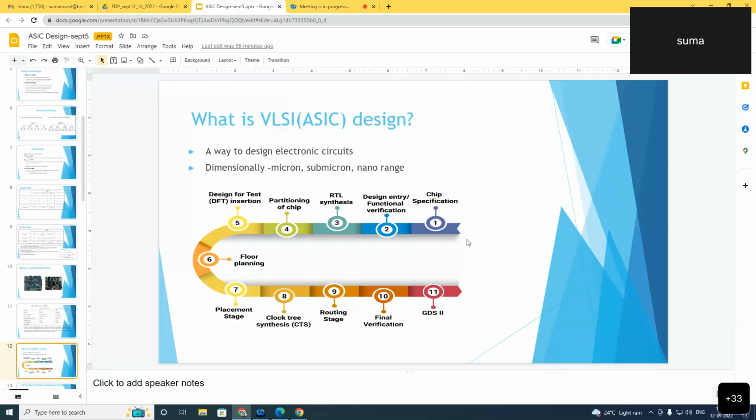Power also depends on the material used to fabricate the IC, and we have so many new technologies like silicon on insulator, which help in power optimization. But the major component of power dissipation, as we see, is due to the switching, that is the transition of signal from high to low and vice versa, which causes the capacitance to charge and discharge.